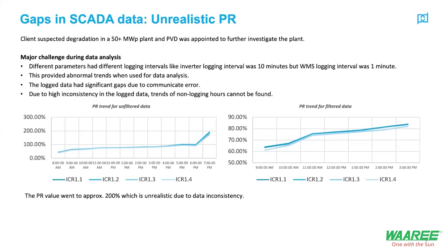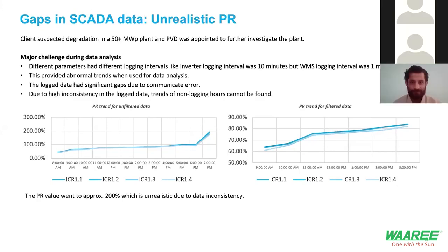A lot of times the issues are in the SCADA itself, because of the data logging and the intervals at which it is collecting. Let's say if there are 10 inverters, you are getting data from 5 inverters and not from the other 5. Now if I compare all of these inverters together, it will lead to random information. It may look like these 5 inverters are underperforming, but that is really not the case. So filtering and analyzing this data properly is really important.